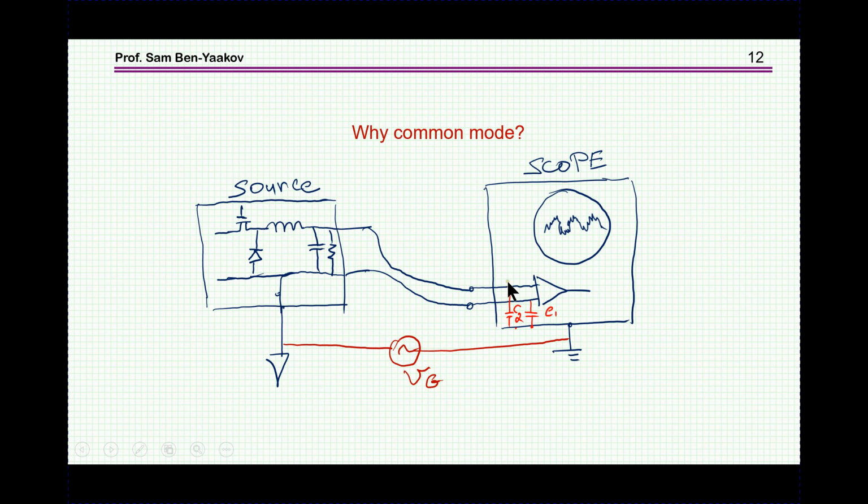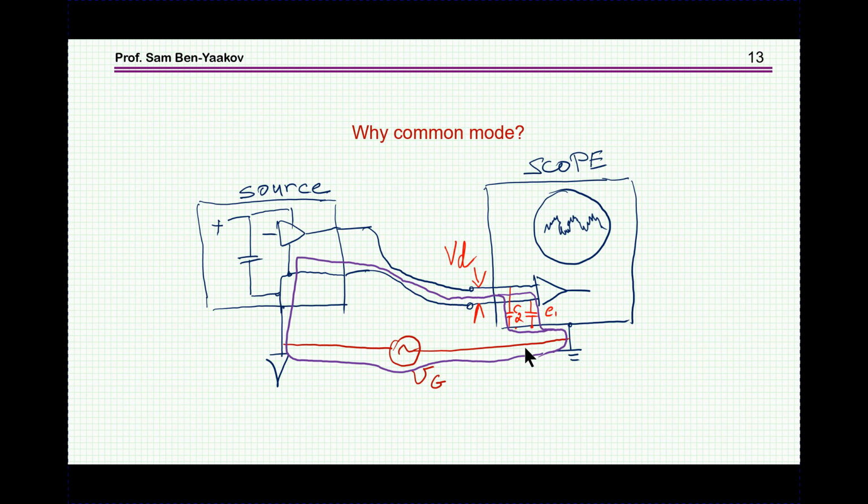So I'm connecting these two to the output, but as it turns out, between any two systems or any two cards or PCB cards, you will have a difference in the potential between the two grounds. There's no escape from that. So if we look at the possible current paths, through this potential difference, we have a current going into the two wires.